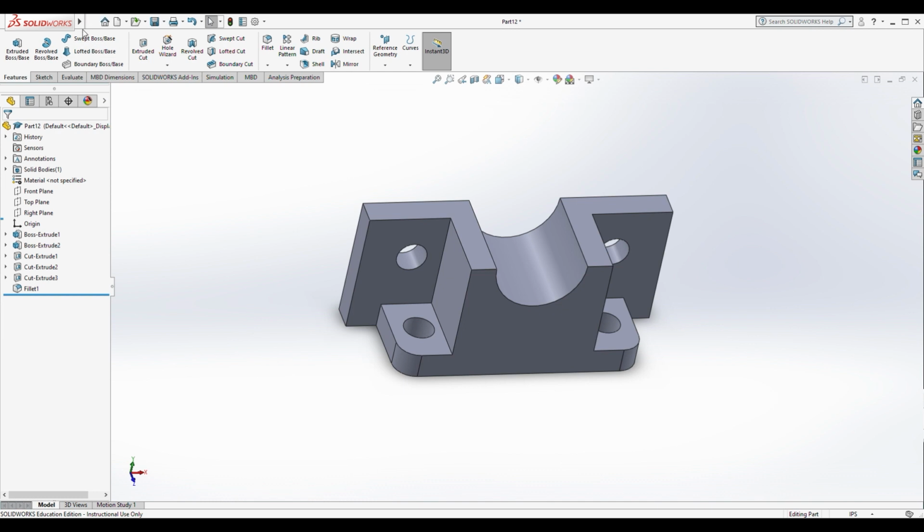So we're good. I'm going to save this as a JPEG, so I'm going to go File, Save As. Now again, if you're going to work on it tomorrow, save it as a Solidworks part, okay? But this one happens to be done, so I'm going to scroll all the way down to where it says JPEG, and this is 3D part 1. Looks like I already have one saved there. And we're going to go ahead and hit save and just replace the other one.